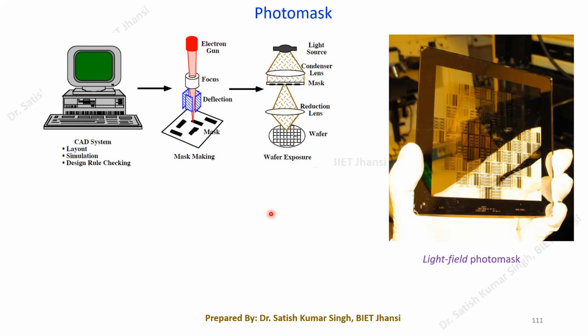So we have to perform a lithography operation again, but this technique is a direct writing technique. In the optical photolithography that we do onto the wafer, we have a photo mask and a light source. The light passes through the photo mask, and through those regions that are transparent to the light, it penetrates and goes to the wafer.